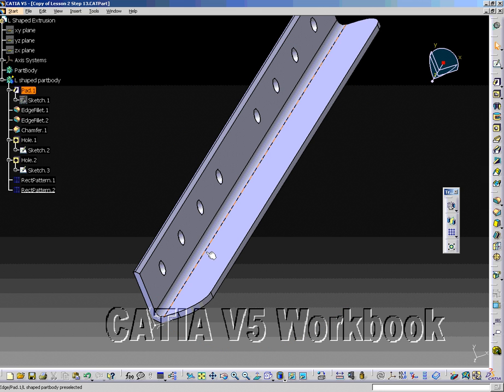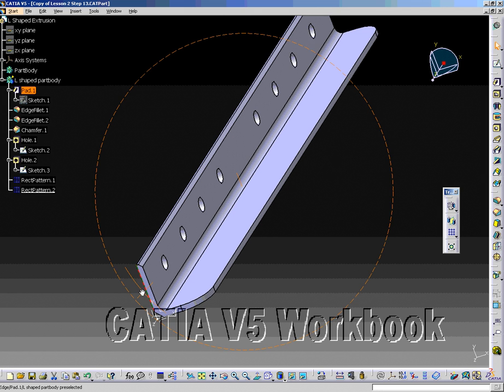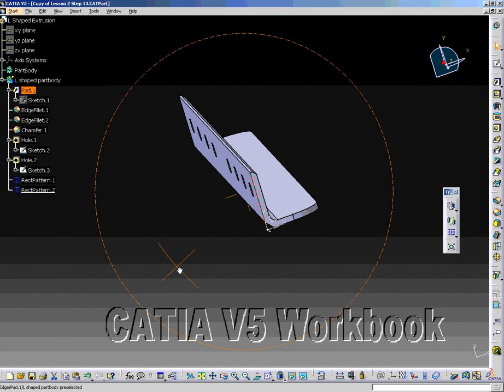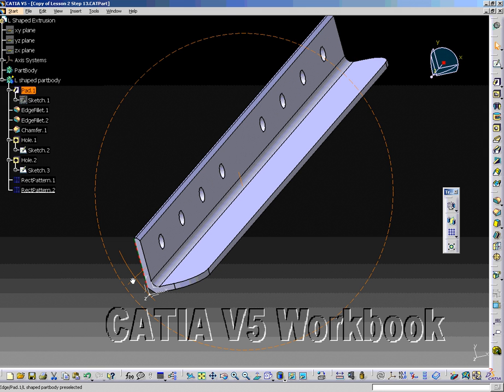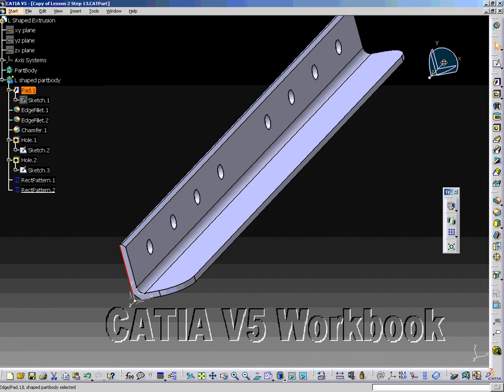To use this command, select the Rotate tool. The tool will highlight red, meaning it has been selected. Select any point on the screen and hold down the left mouse button. The rotation sphere will appear and show the axis of rotation. When you have rotated your point of view to where you want it, release the left mouse button and the rotation will be terminated.